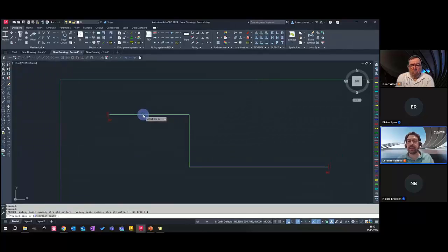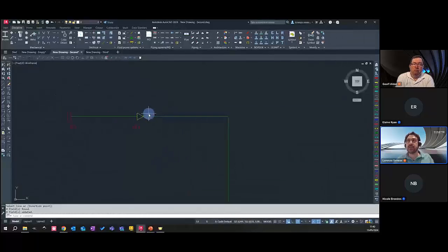So the thing that I said is smart is the one that I'm going to show you right now: if I'm placing that valve in here, it is also trimming my line and placing the block in here. And again, there is the numbering system. If I want to copy this into another position, I can use a Sovelia feature, so I don't need to reopen my library. I can just copy this one and place that in another position. And you can see it is also orientating accordingly with the piping line. I can do that one more time in there and place that in here.